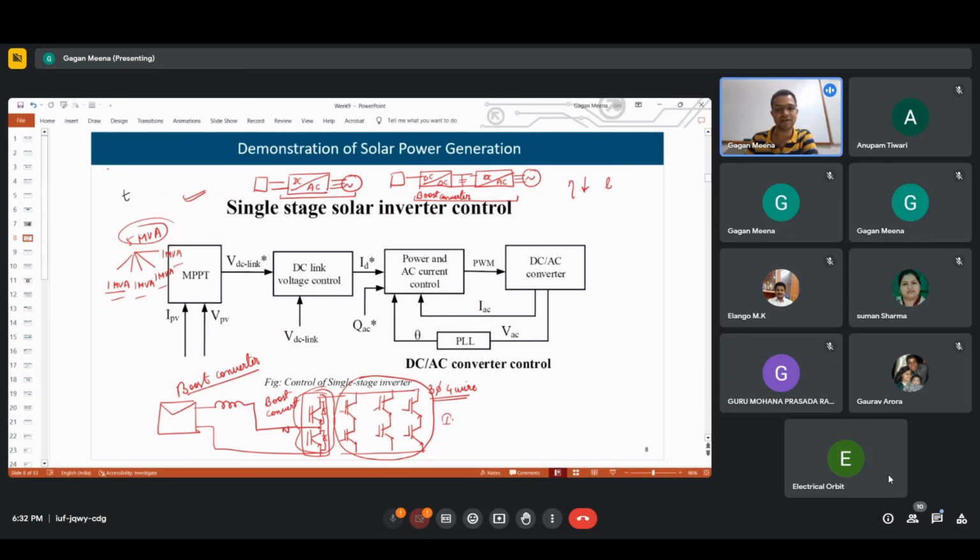And access oriented means they should give fast, quick access. So for them we need high power density. Their response is fast. They can respond to short-term disturbances, such as providing inertial support for primary frequency response. So flywheel, supercapacitor, and superconducting magnetic energy storage can provide these access-oriented services.